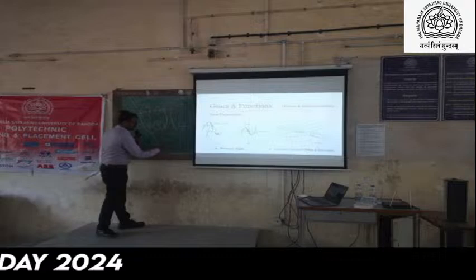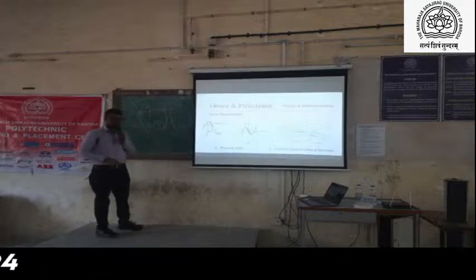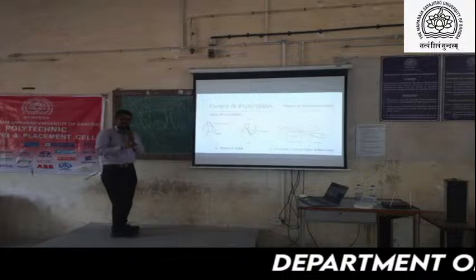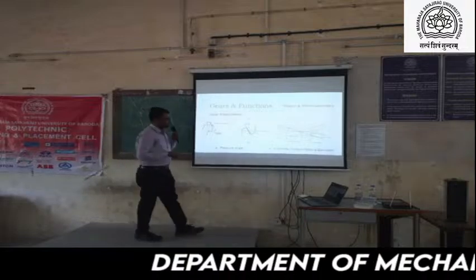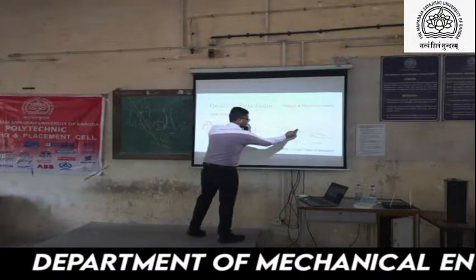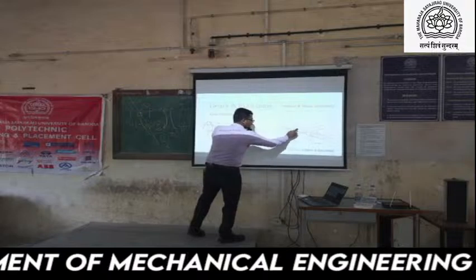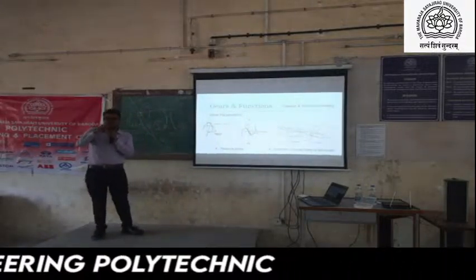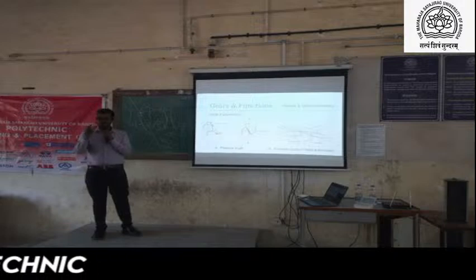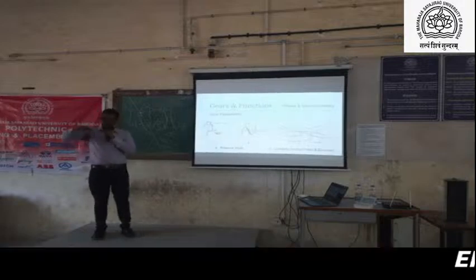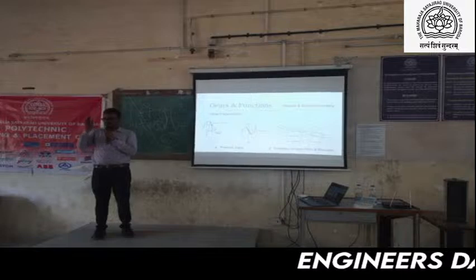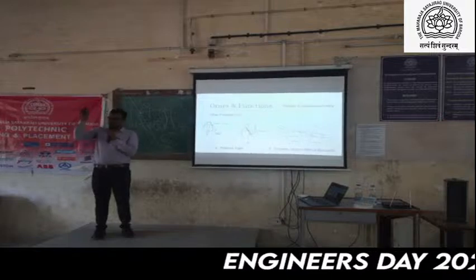But 1 is in full contact, 2 are in partial contact. Yes, no? Even the full tooth is not fully getting contacted, because of the active contact length. So just 60% is getting contact in a single tooth. Then what about the other two? Just 40%, partially getting contact and partially getting removed.